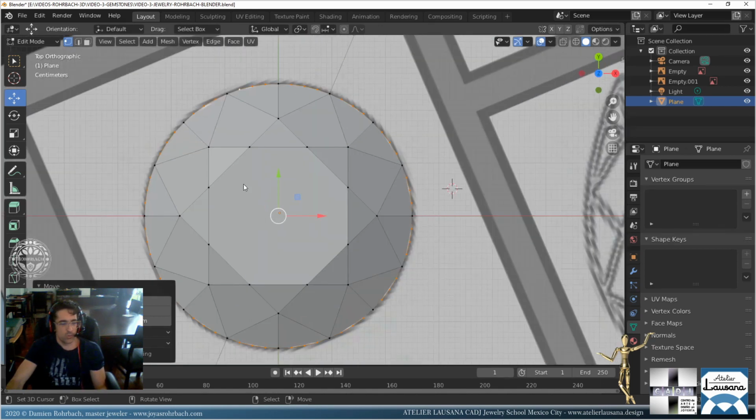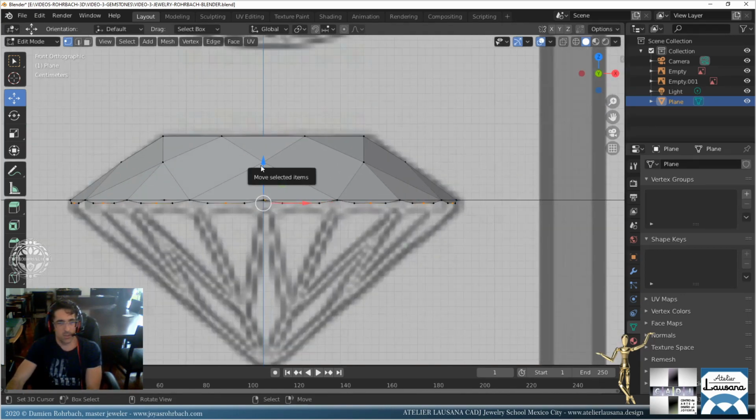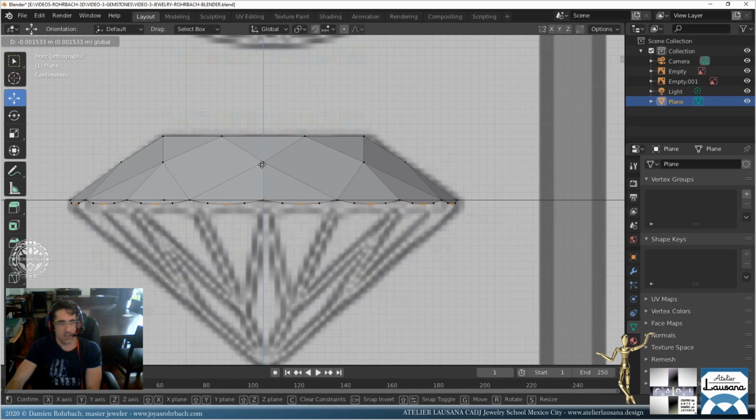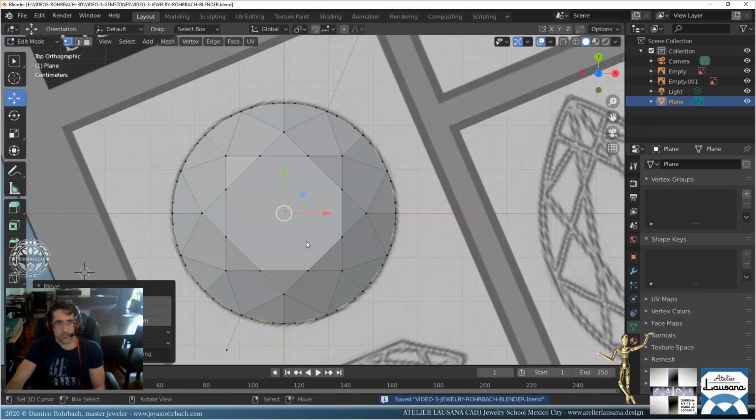Now I'm going to remove, so let's go to C, but with the shift key, I'm going to remove the sides and just keep the middle one selected. Okay, C. So it's C for the circle selector, then shift to remove that. So I just have the middle vertices, and let's move it down a little like this.